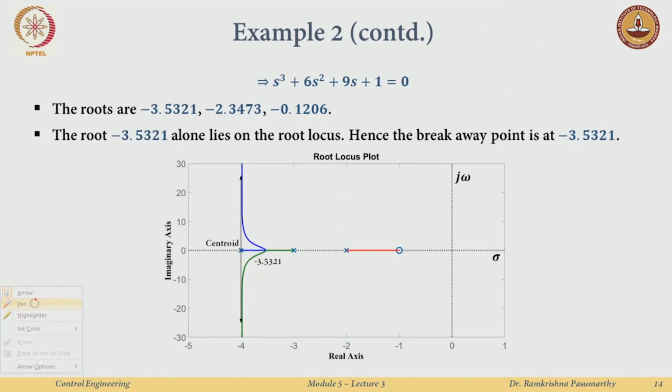So, what happens is, from the asymptote and centroid computation, I know that these two branches will meet these two lines at infinity. So this one starts here and goes to infinity along this line, and the other starts here and goes to infinity along the other line. That is the way we compute. Why do they not do something like this, or something like this? That we will see a little later, but at the moment we are interested in the asymptotic behavior.